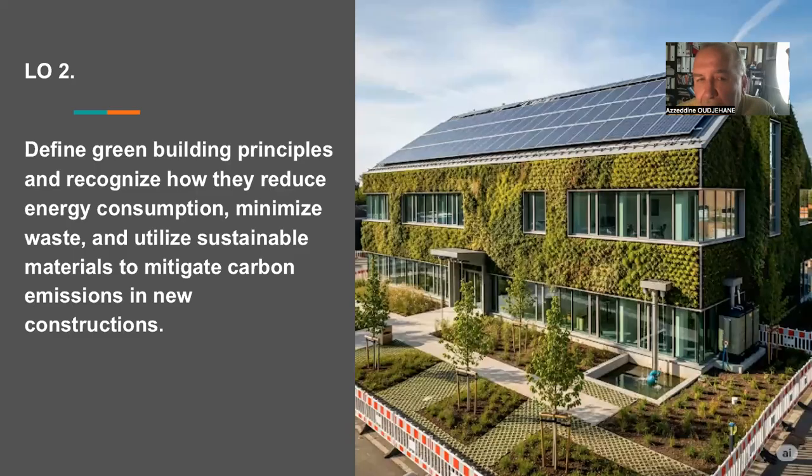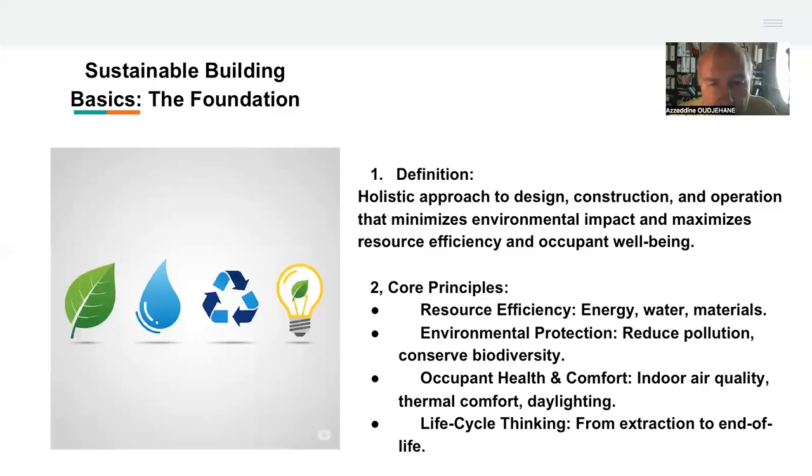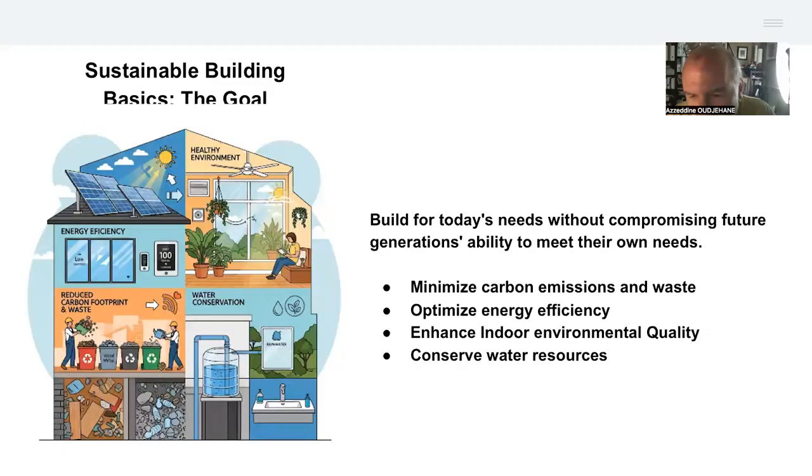So when it comes down to green building practices, what are the foundations? What are the basics? The basics are around 3 or 4 points. For a new building, the foundations are about designing, constructing, and operating with the maximum efficiency and the minimum impact to the environment. What does that translate into when you want to design a new building? It is the integration of those concepts at the beginning in order to minimize carbon emissions and waste and optimize energy efficiency for the usage of lighting, heating, cooling, and so on.